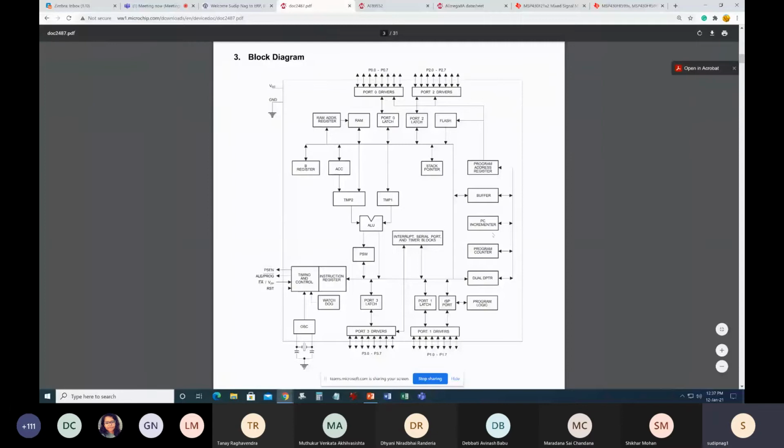They are splitting the program counter into multiple sub blocks, that's why you see 3 blocks here. The program counter is a 16-bit register similar to the stack pointer, but in addition you have to increase it and then keep it back. That's why you need an up counter, the PC incrementer. You can say this is a misnomer: program counter is the name of a register, it's not actually a counter. The counter is present in the incrementer.